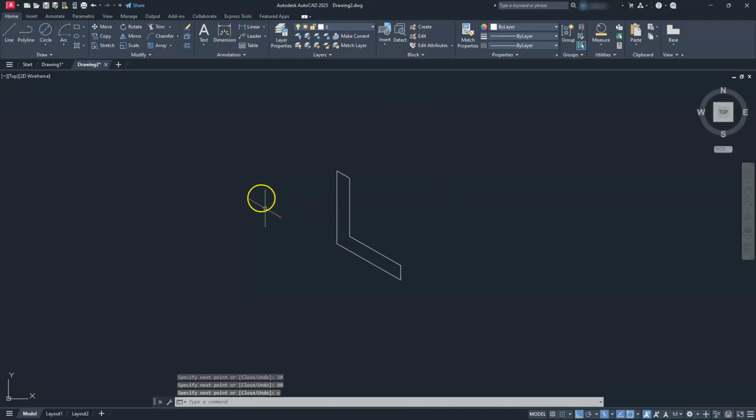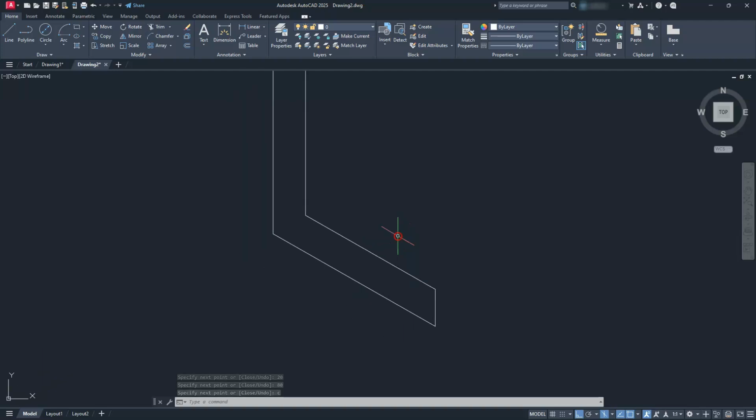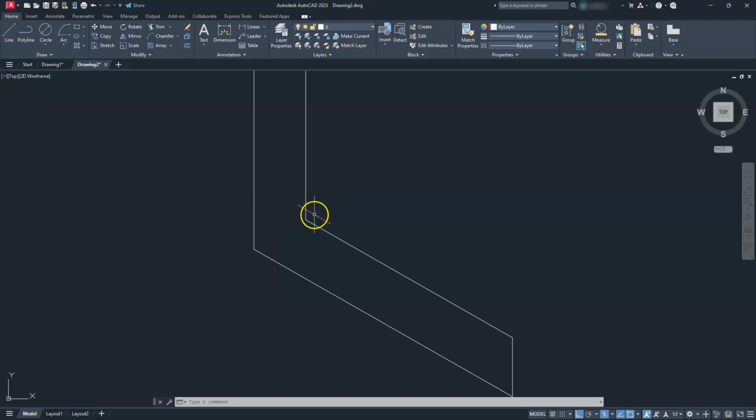All right. So this is all the normal stuff that we did in the first thing, right? Next, let's go ahead and create this ISO circle here. So I'm going to go to ellipse, and remember that we have to type it in. So EL, enter, and then we'll get the option for an ISO circle here on my command line. I'll just type I, enter. And then I have to locate the center of it. I'll go ahead and place it right here on this center at that endpoint, expand out and give it a preview. And then the radius of it will be set to 10.